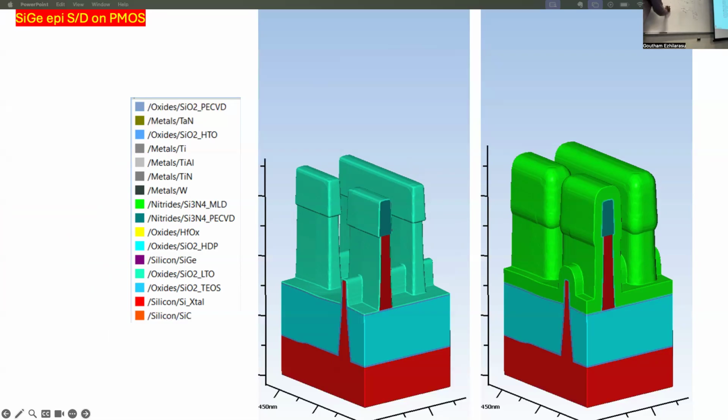And the silicon germanium is in situ doped. So if this is an NMOS, this is in situ doped N plus, right? And this will be N minus. Sorry, this will be silicon carbide for the NMOS. And what this is going to do is create a tensile stress on the transistor, and on the channel, and that's what's going to create your enhancement in the electron mobility, right?